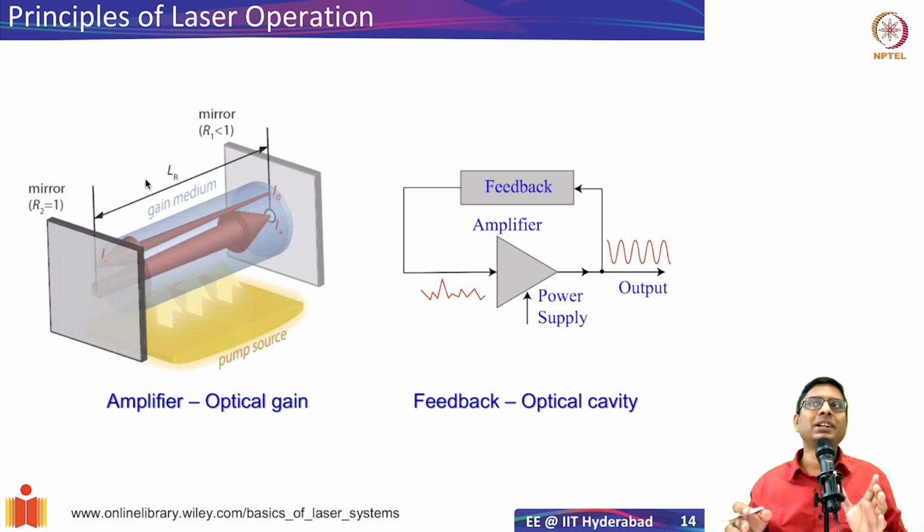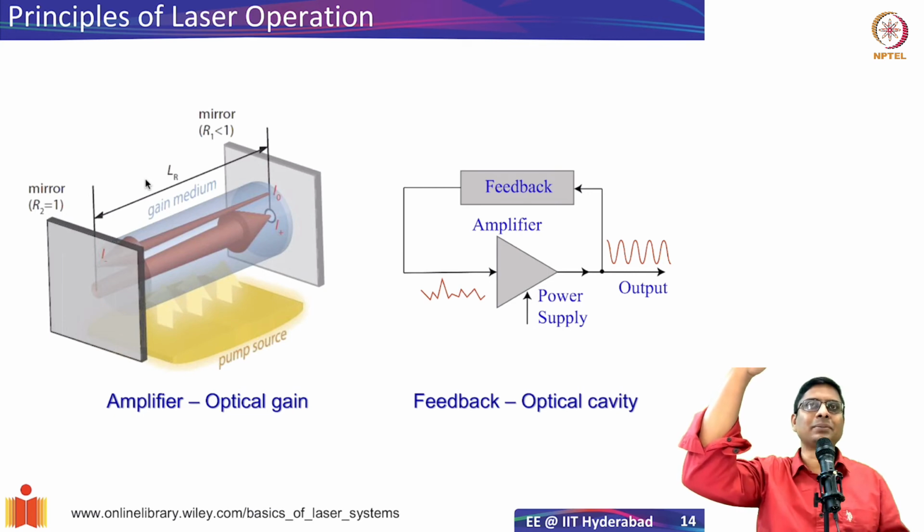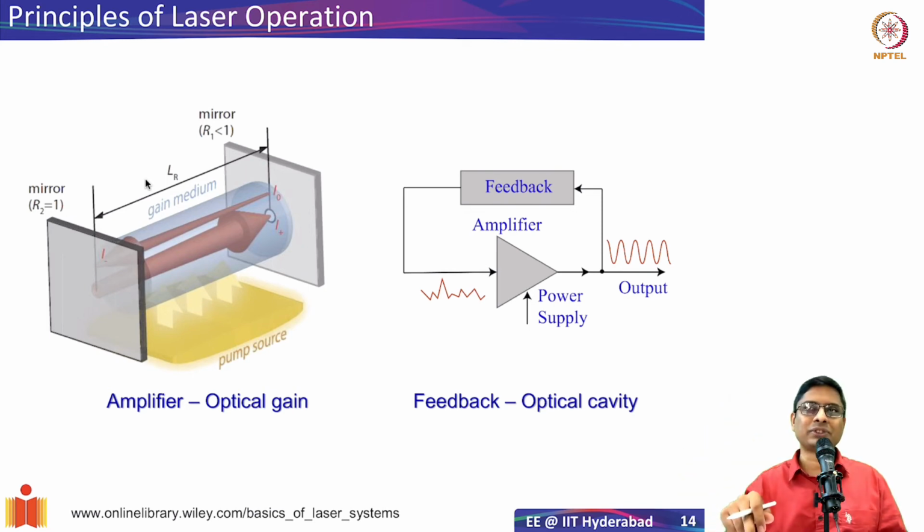and then you put in a gain medium. A gain medium is like a two-level system or excited semiconductor, whatever. You put in a gain medium which is actually having gain, not loss. By default, if you look at any material, it is never going to have gain, because the distribution of atoms follows the Boltzmann distribution. So the excited state will always have fewer carriers than the ground state. So you will only have absorption. But I have to create a situation, and we will talk about that, which we call population inversion. Only in that scenario will you have gain.